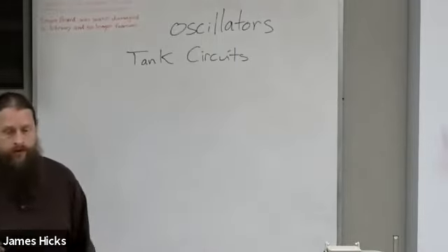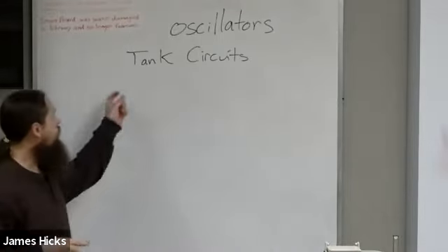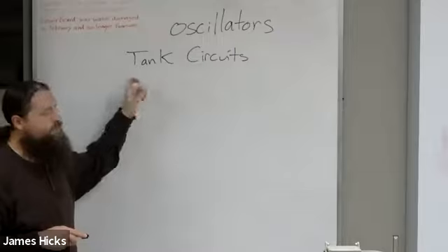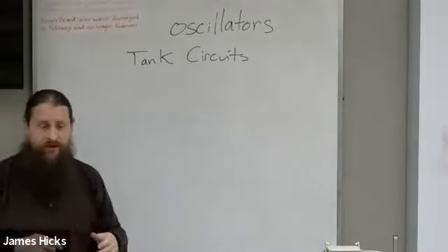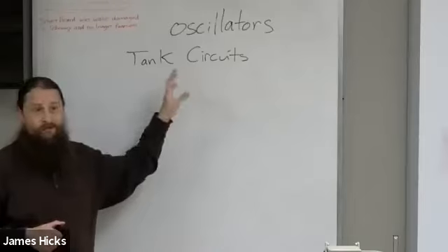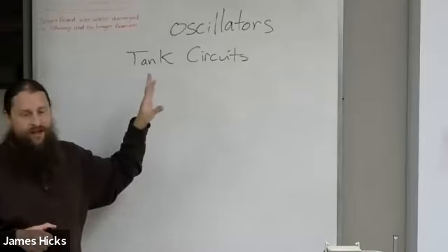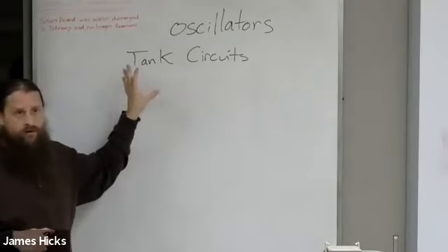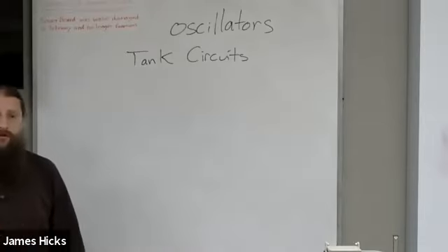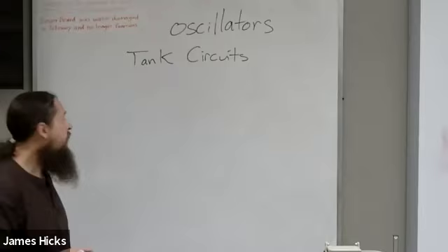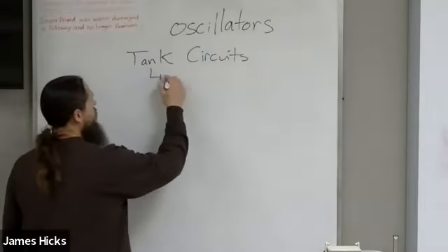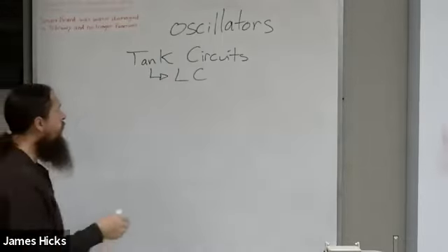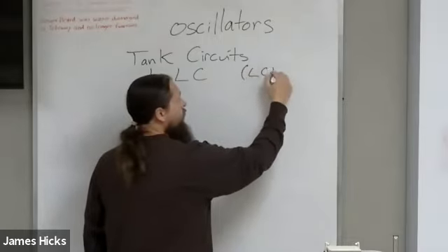So I want to talk real quick about tank circuits. This is a term you see a lot in electronics, especially with oscillators. And for me, it took way longer than I had wanted to figure out what was meant by a tank circuit. So I wanted to start there, because this is going to provide the basis for a lot of oscillator circuits. So this tank circuit is some kind of inductor capacitor circuit or inductor capacitor resistor.